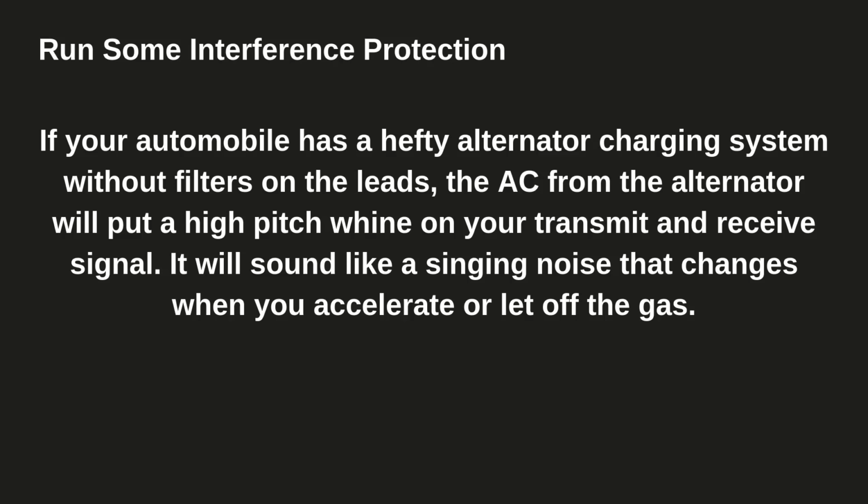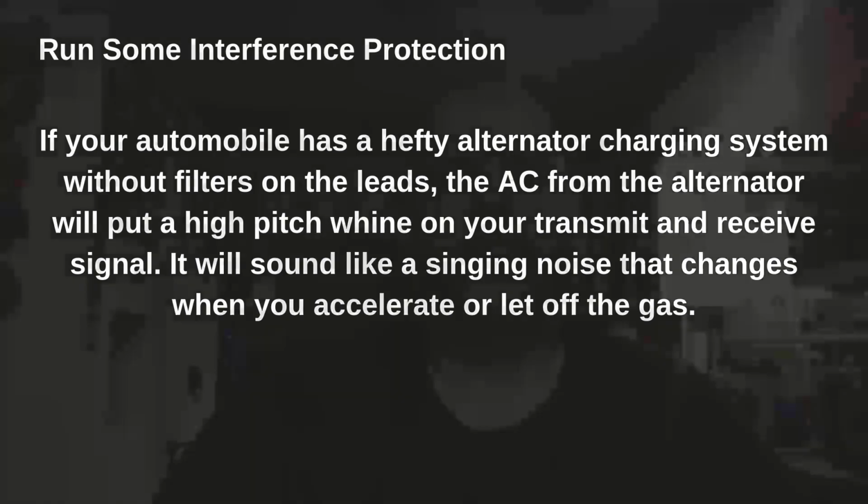Alright, here's a fun one. If you have a mobile radio in your vehicle, and your automobile has a hefty alternator charging system without filters on the leads, the AC from the alternator will put a high-pitched whine on your transmit and receive signal. It will sound like a singing noise that changes when you accelerate or let off the gas. And we're going to go to Donald real quick.